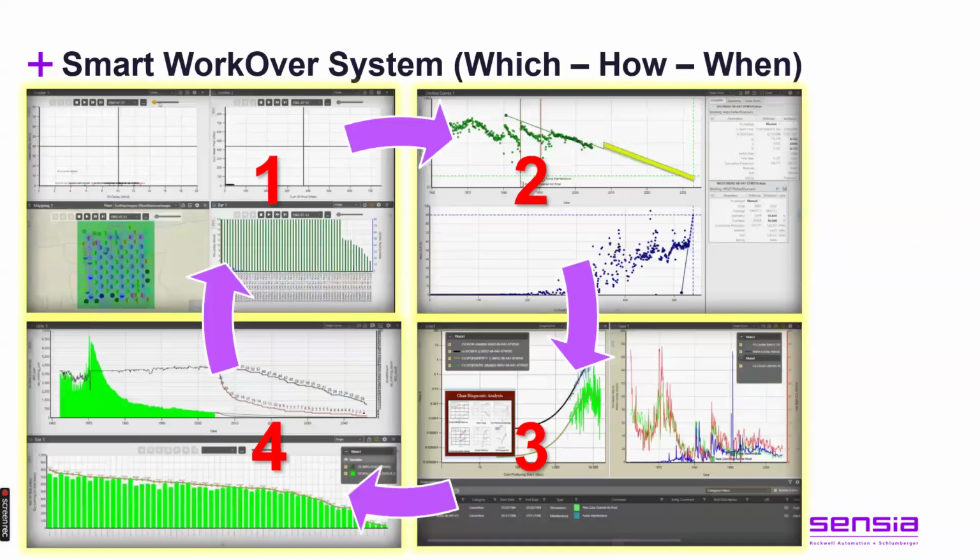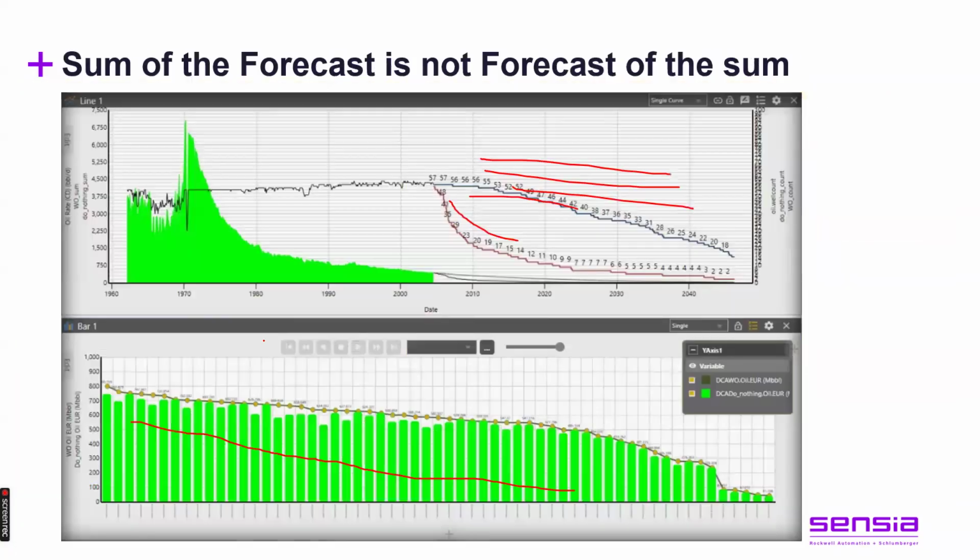Now we reach the final step where I show all my wells, which is the field level now. You can see my field, in the beginning I start to increase my production, which is normal. And then I get a plateau where I have a constant or stable rate. And then my field starts to decline, right? And this is dangerous, right? Because I have to do something now because I'm losing.